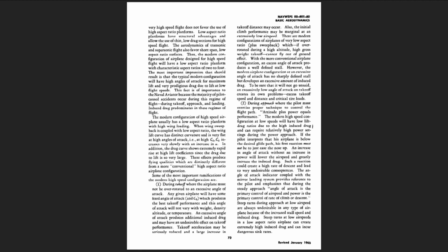During takeoff, the airplane must not be over-rotated to an excessive angle of attack. Any given airplane will have some fixed angle of attack, and C_L, which produces the best takeoff performance, and this angle of attack will not vary with weight, density, altitude, or temperature. An excessive angle of attack produces additional induced drag and may have an undesirable effect on takeoff performance.